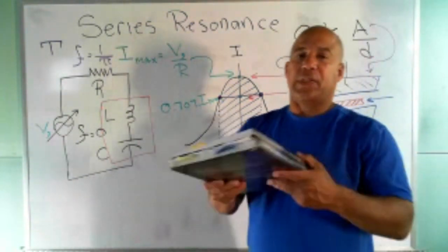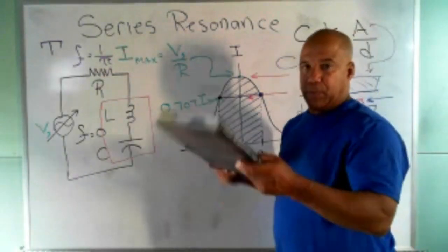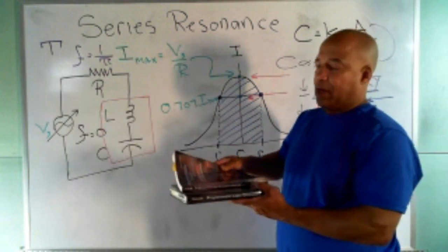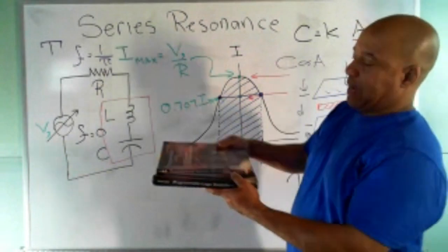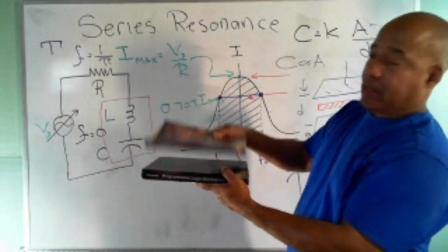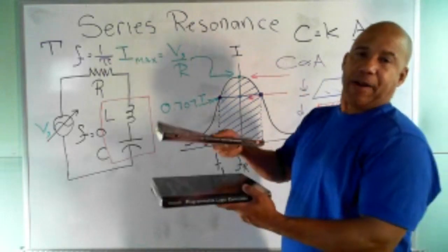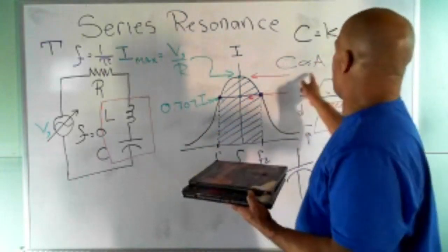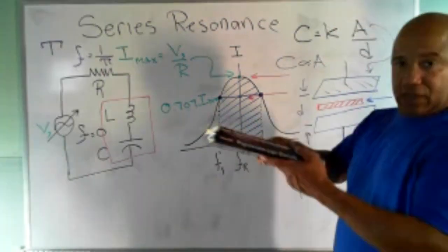But anyway, suppose these were metal plates. This plate and this plate, this book and this book, they're plates, right? And I got the leads connected to it. So I have a capacitance. So all I got to do to use this formula is measure the distance between the plates, measure the area of the plates, and then figure out, like my dielectric here is air. So I think air has a dielectric constant of 1. So I just put a 1 in for that. So if I measure this area and the distance, I can get the capacitance of this capacitor I'm holding in my hand.